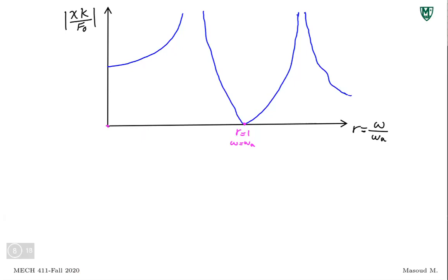So when the excitation frequency has exactly the same frequency as my absorber, all the force is transmitted to the absorber, so no energy is going to stay in my primary structure. Now, how do we get the performance of our system from this? Again, that was the main question we're trying to figure out: for which range of frequency this absorber is good, and for which range it is useless.